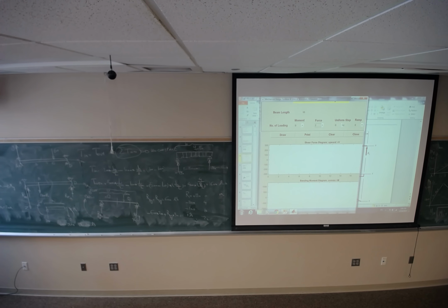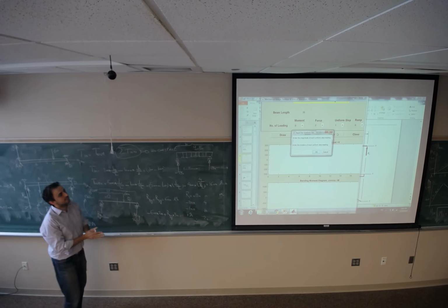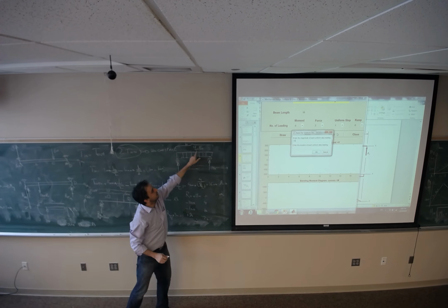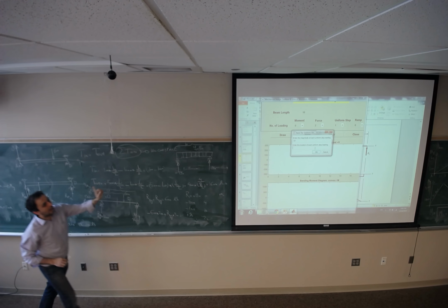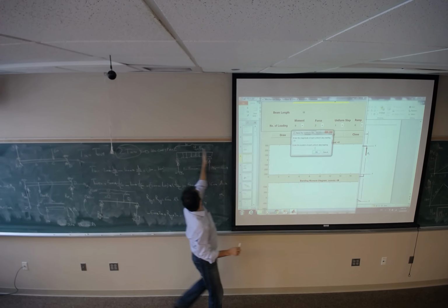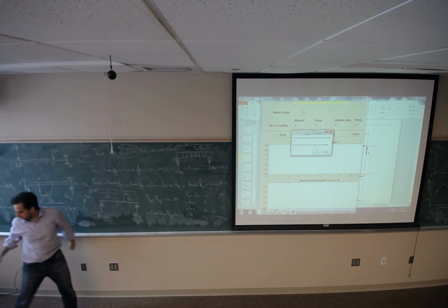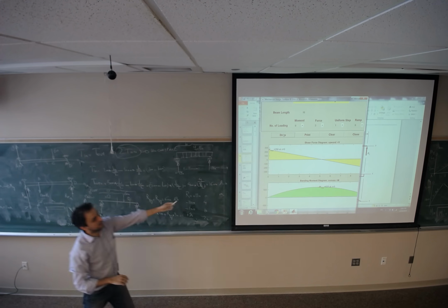And we have one uniform step. The first one is asking you for the load density, which is negative 50 because it goes down. Don't forget about the negative. And the second one is asking at which point it's going to start. The distributed load that we have is going to start at 0. So then you will get something like this.